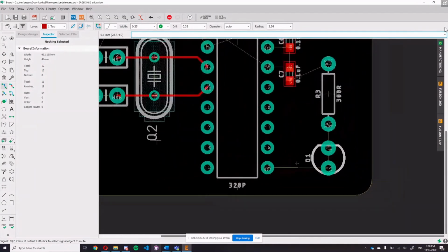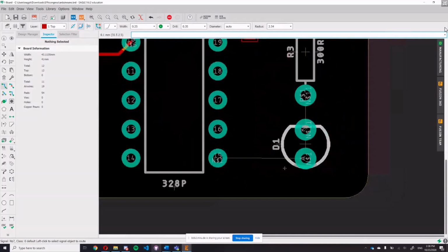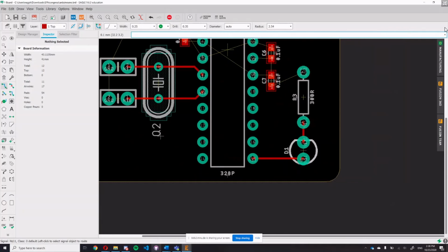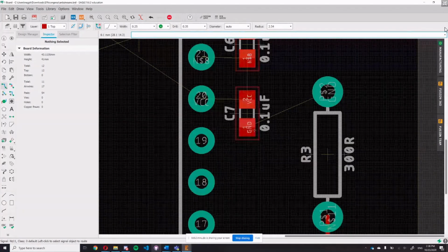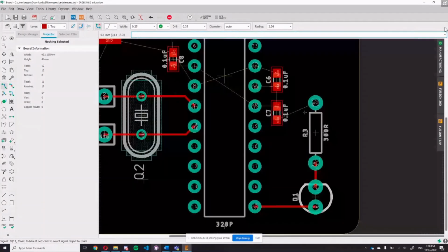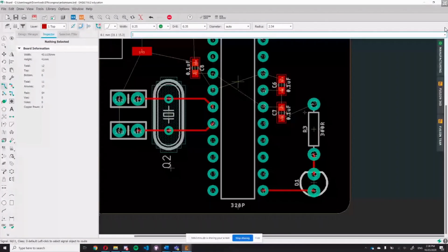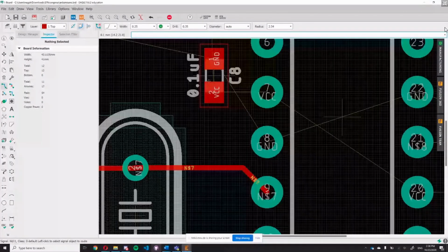So let's move on to the LED phase. The LED is actually going to pull some current, but not really much, so we can use the same trace width. So we put a trace here, and not here. We do not connect ground yet. I will explain that later.